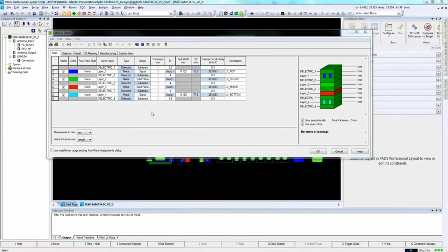With a complete power plane as close as possible to the ground plane, it's possible to create capacitive coupling between them to get low impedance at high frequencies. This reduces the amount of small decoupling capacitors at the power pins of the devices. The closer the planes, the less impedance is present.